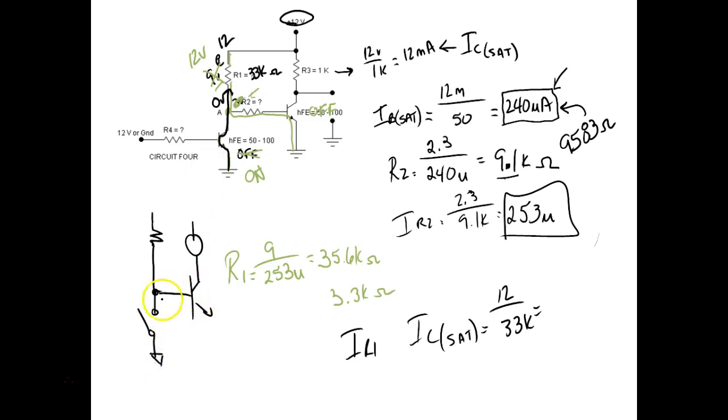The transistor cuts off. When the switch is off, this transistor cuts on. What we're doing here for this switch is we've moved this resistor right there, and then this resistor would be the resistor for this transistor right there, right? You understand that? So when this guy cuts on, that puts 0 volts right there.